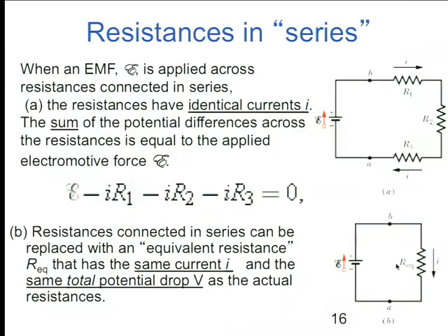And so the equivalent resistance is this, because I want to get the form E is equal to I times the equivalent resistance. I want to make it into one resistor. So the equivalent resistor of this circuit is simply the source EMF with its R equivalent, one resistor, which is R1 plus R2. In other words, they just add up numerically. That's the easy case. The harder case is when they're in parallel.